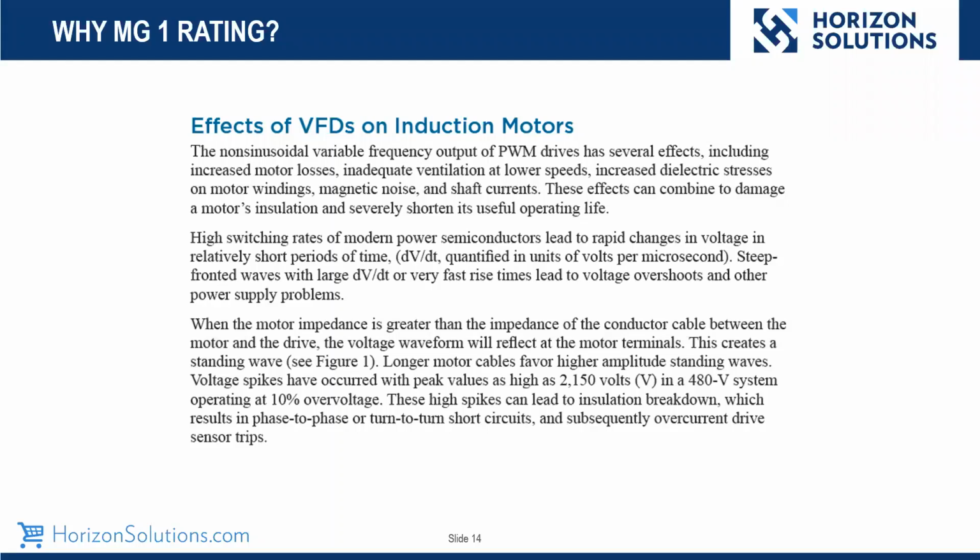This is very, very interesting because, at a 10% over voltage on your drive, and saying your voltage is higher going and being rectified into the drive, you're going to see higher switching values. So it's also important to try to keep your voltage on your VFD down near the nominal rating of 480 volts.